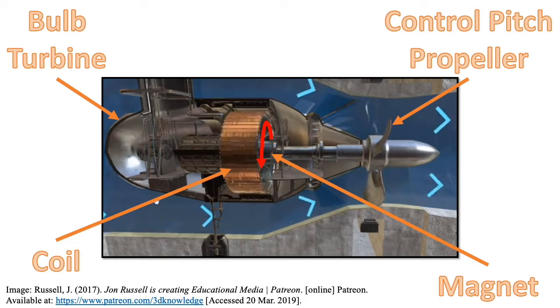Allowing a potential head to accumulate before opening the sluice gates generates an increased flow rate through the aperture compared to that of the nominal tidal flow rate. This drives the propeller shaft, rotating a magnet which induces an electrical current across the surrounding coil.